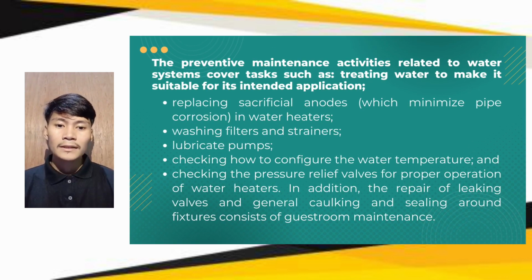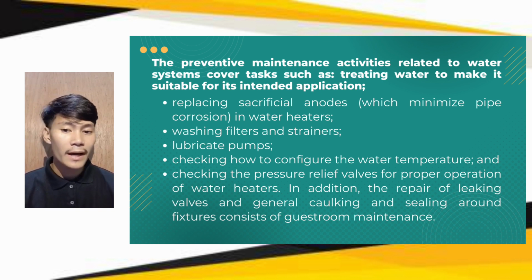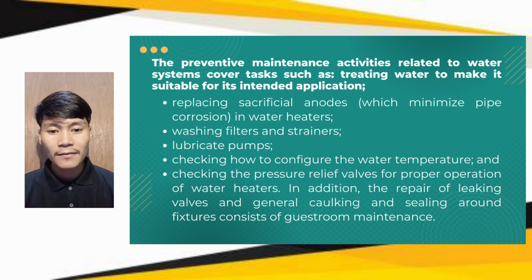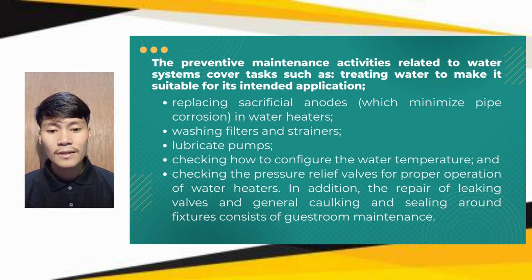The preventive maintenance activities related to water system cover tasks such as treating water to make it suitable for its intended application. First one, replacing artificial anodes which minimize pipe corrosion in water heaters, washing filters and strainers, lubricating pumps, checking how to configure the water temperature, and lastly, checking the pressure relief valves for proper operation of water heaters. In addition, the repair of leaking valves and general caulking and sealing around fixtures consist of guest room and maintenance.